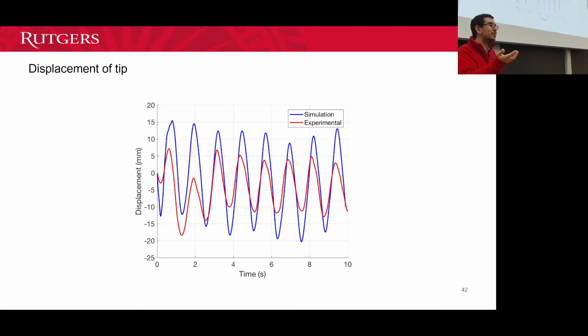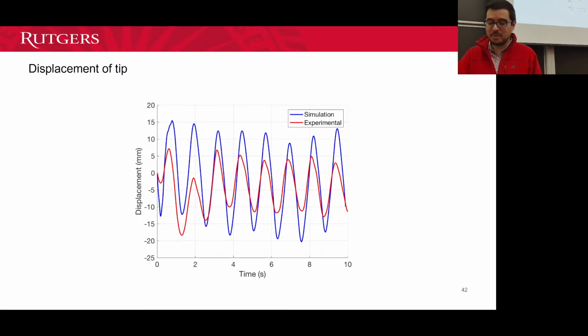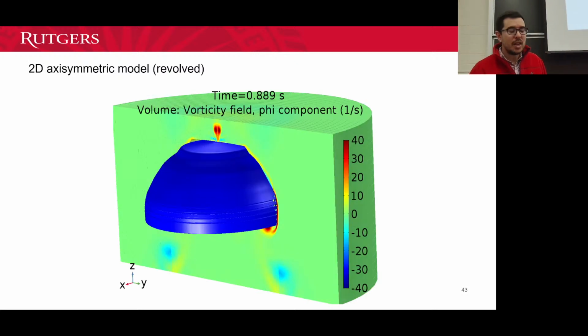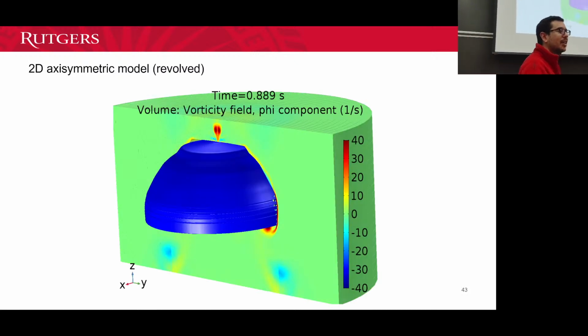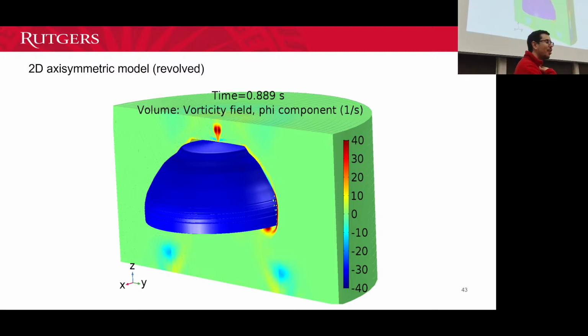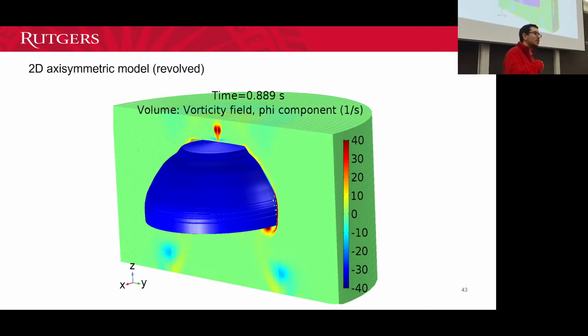When we do our fluid structure, when we do any of our CFD simulations, if we're within 10%, we're jumping up and down, okay? Because we're pretty close. And people can do higher fidelity simulations. Don't think that our CFD simulations in this course this semester are the end all and be all of simulations. We were just doing 2D stuff mostly, not using a whole lot of elements, and they're solving in minutes, not hours or days, okay?